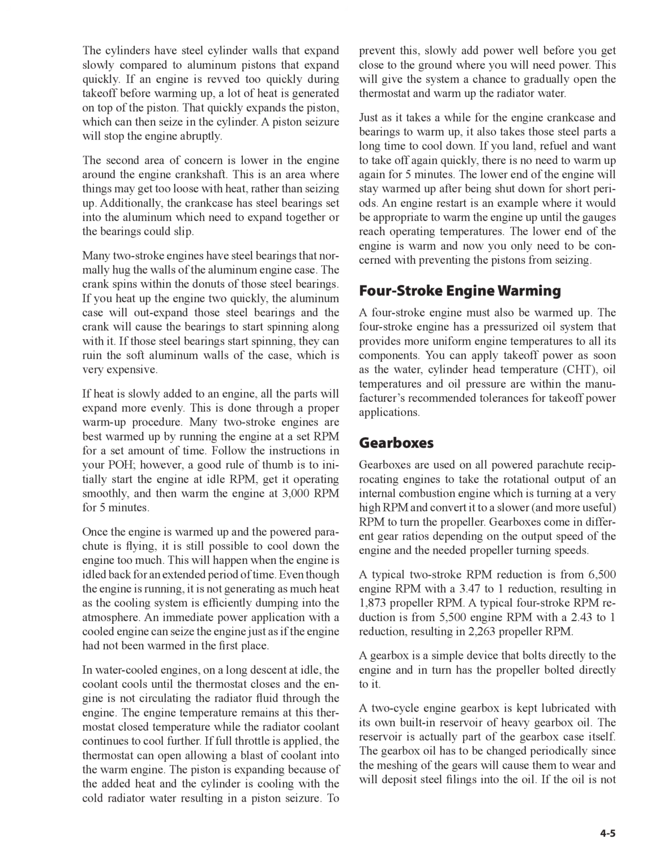An engine restart is an example where it would be appropriate to warm the engine up until the gauges reach operating temperatures. The lower end of the engine is warm and now you only need to be concerned with preventing the pistons from seizing. 4-stroke engine warming. A 4-stroke engine must also be warmed up. The 4-stroke engine has a pressurized oil system that provides more uniform engine temperatures to all its components.